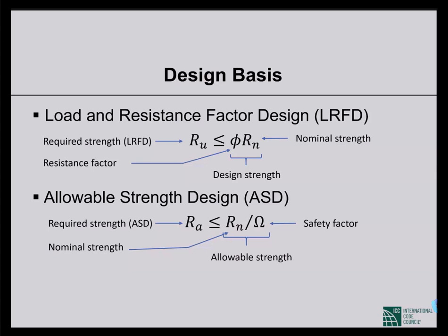Now, there is another design method that is also allowed, which is allowable strength design. Be careful, the term is strength, not stress. In ASD, the term is allowable strength design. But previously in BNBC 2006, what we had was the working stress design method. These are two different things.